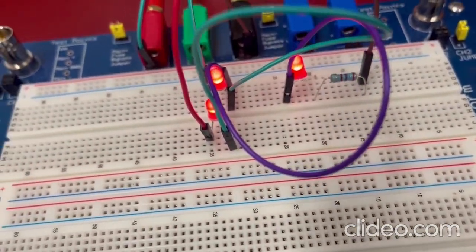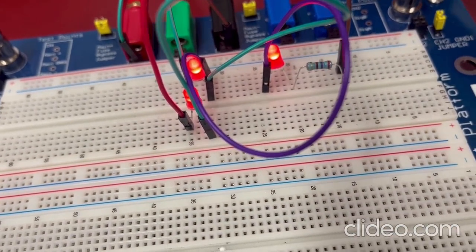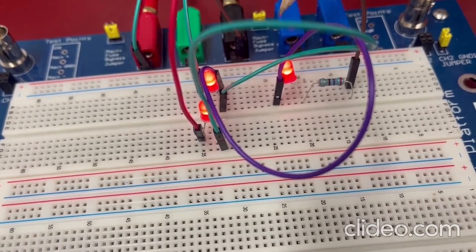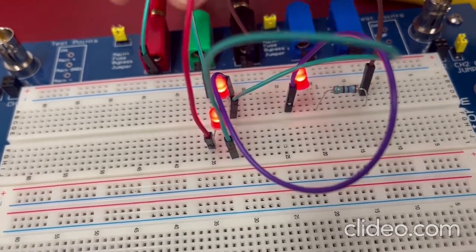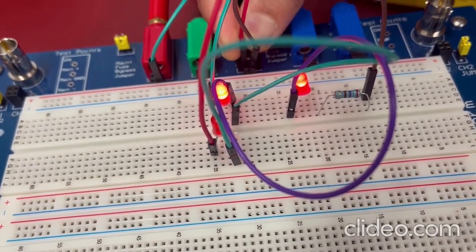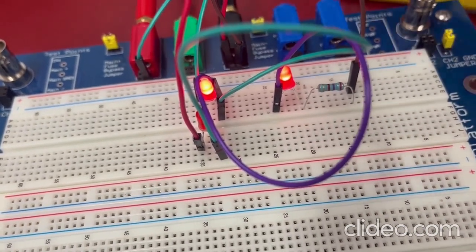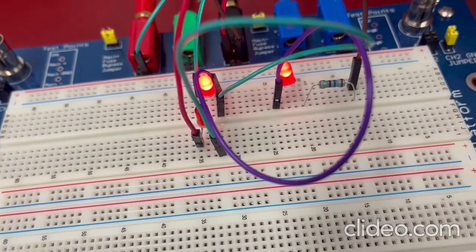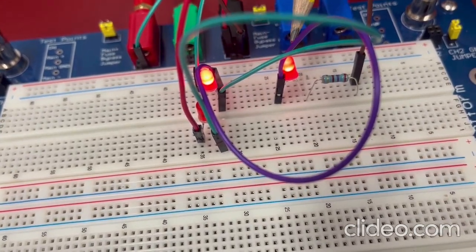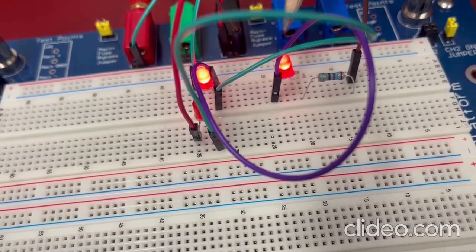When we switch on the supply, when both of the inputs are connected to VDD, you can see my output is high. So let me change one of the inputs to ground. The green input is still connected to high, so that LED is on, but the second LED becomes off, and my third LED, the output LED, is still glowing.